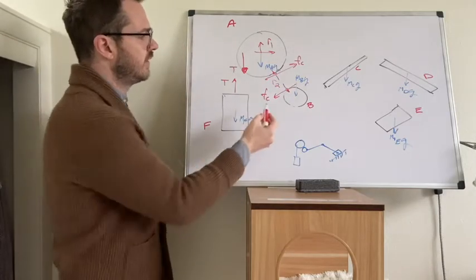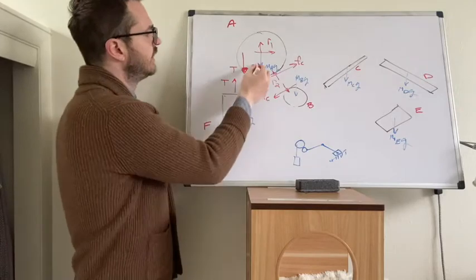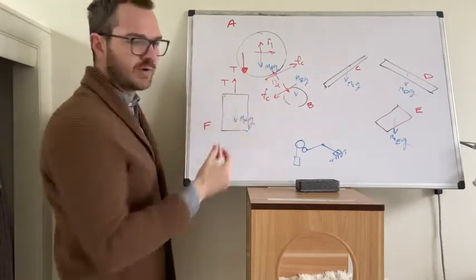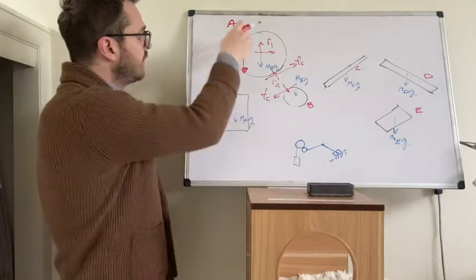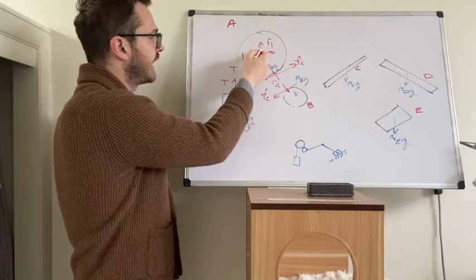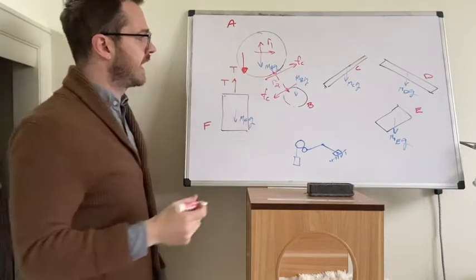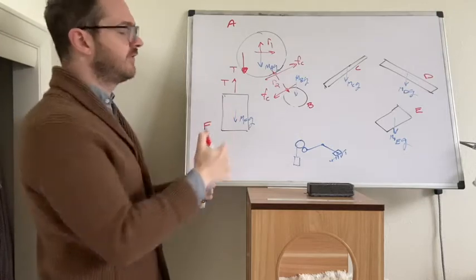And remember, equal and opposite, right? So if we put it in a particular direction on body A, it has to be in the opposite direction on body B. Next, what else is going on with A? Normal force, friction force, reactions here, tension, and gravity. As far as what has to be on the diagram, that's good for body A.